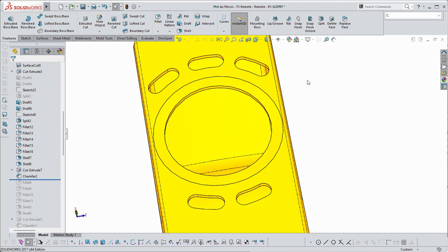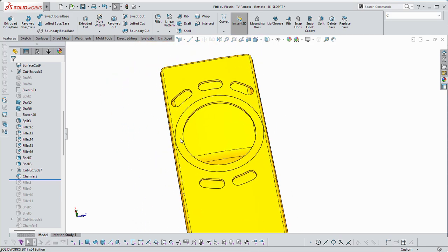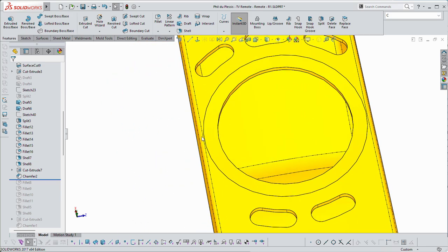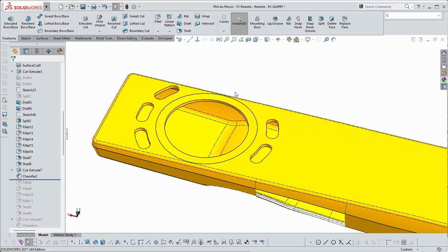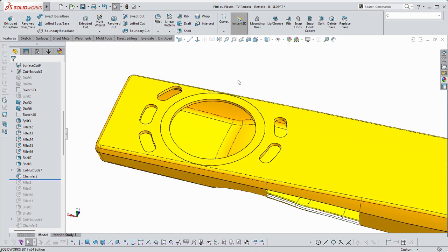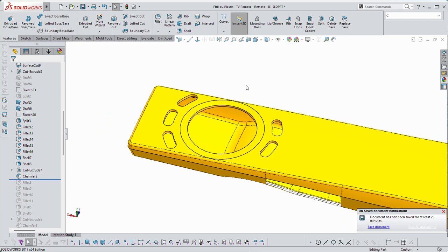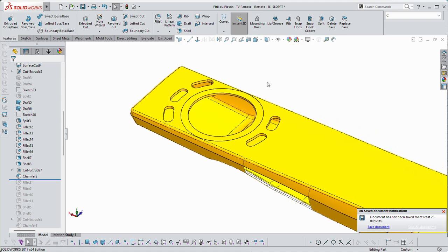3. Perfect. Okay, so you definitely don't want the chamfer to interfere with this fillet. That's difficult to tool, and it's just bad modeling. Don't do it. All right, and that's it.